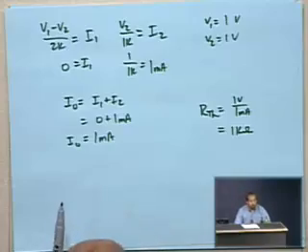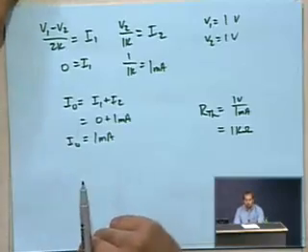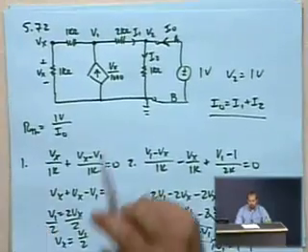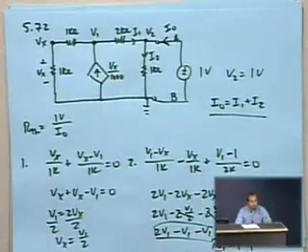So what that means is that practically speaking, if you have this circuit and you want to know the Thevenin resistance of that circuit, because I want to stick it in someplace and see what happens, and I want to analyze it ahead of time, well, I could stick a 1K resistor in there and it would give me the same behavior, as long as I didn't screw up any of my math.